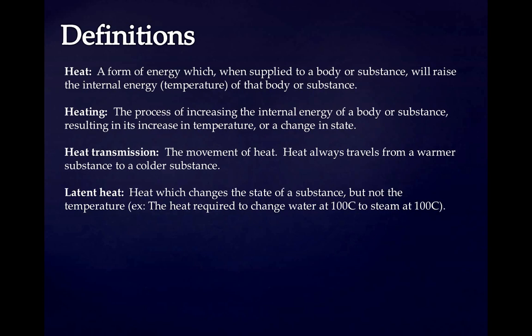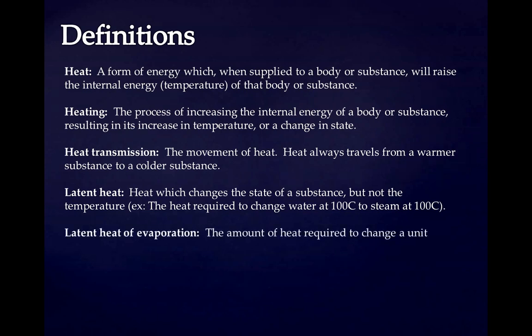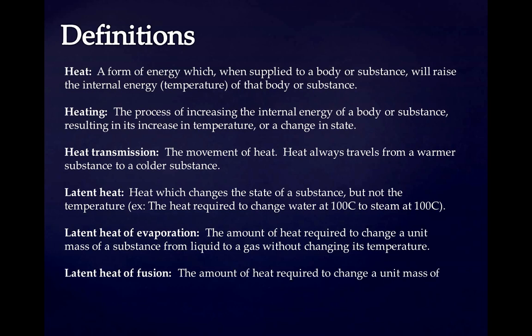Latent heat, heat which changes the state of a substance, but not the temperature. For example, the heat required to change water at 100 Celsius to steam at 100 Celsius. Latent heat of evaporation, the amount of heat required to change a unit mass of a substance from liquid to a gas without changing its temperature. Latent heat of fusion, the amount of heat required to change a unit mass of a substance from solid to liquid without changing its temperature.